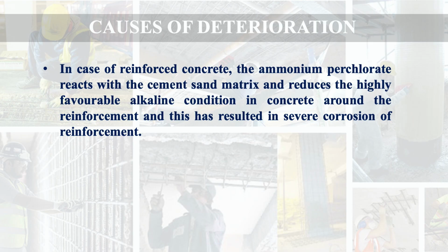In case of reinforced concrete, the ammonium perchlorate reacts with the cement sand matrix and reduces the highly favorable alkaline condition in the concrete around the reinforcement, and this has resulted in severe corrosion of reinforcement.